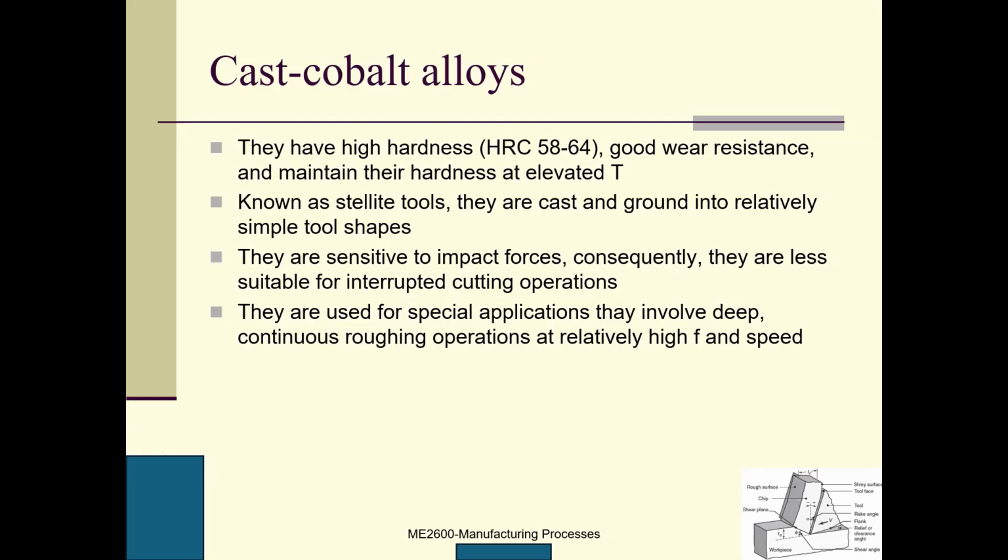They are sensitive to impact forces, and consequently they are less suitable for interrupted cutting operations. For face milling, if the plane being milled is very big, with one revolution after another, it is an interrupted kind of operation. They are used for special applications that involve deep, continuous roughing operations at relatively high feed rate and speed. So this is the cast cobalt alloy for the tool.